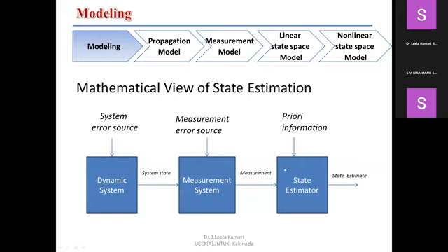Taking these measurements and previous information, the state estimator is going to give you the future state of the system. Suppose xk is the a priori state, and taking the previous measurements and present measurements into account, we get xk plus 1, the future state of that particular dynamic system. So the next position of the satellite is given by this state estimator, taking the previous information as well as the measured information, like estimating velocity from noisy position data, or estimating heart rate variations from ECG in biomedical applications, or estimating channel coefficients in wireless communication, or estimating glucose level in biomedical devices.